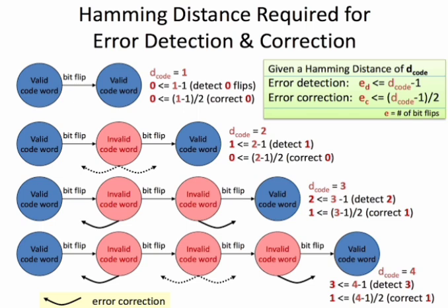In order to reject the image frequency, the bandwidth of the RF amplifier should satisfy BC < BRF < 2FIF, where BC is the bandwidth of the AM radio signal, BRF is the bandwidth of the RF amplifier, and FIF is the intermediate frequency.